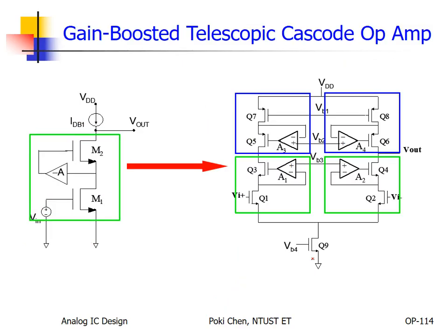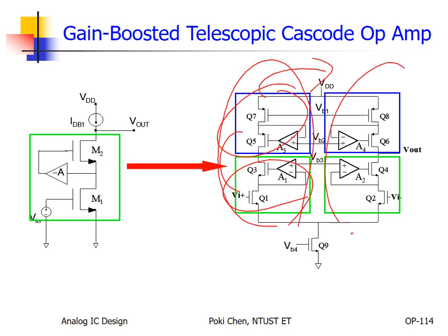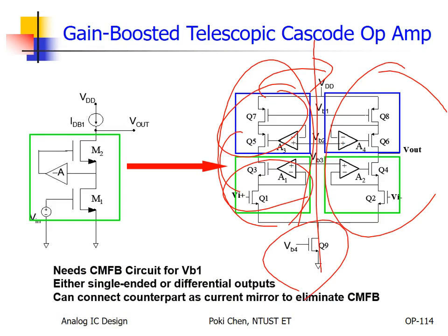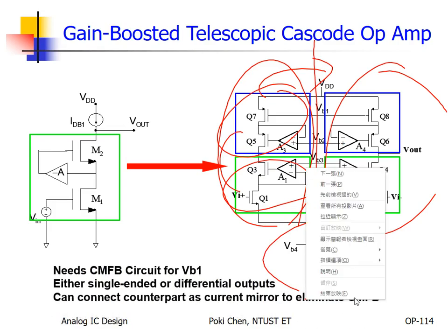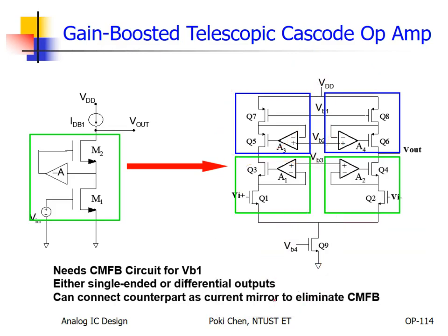That is the easiest. Then the quarter circuit and the counterpart circuit: left half, flip to the right, right half, then in the middle you apply such a bias current. That's it. And again, where to apply your common mode feedback circuit? Inputs are here, right? So to the other end, here. And for the common mode feedback circuit, I will explain in detail later.